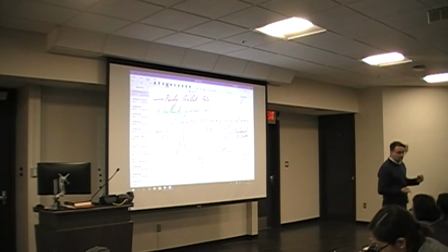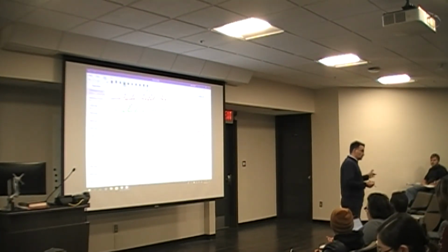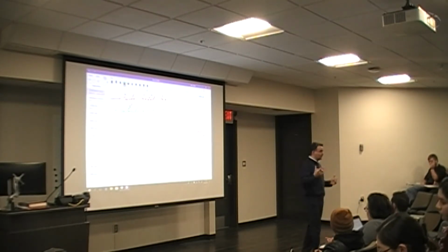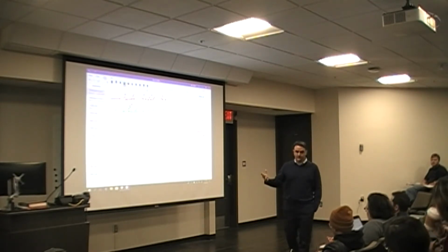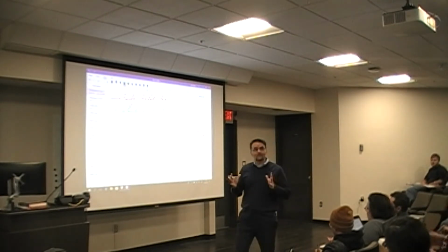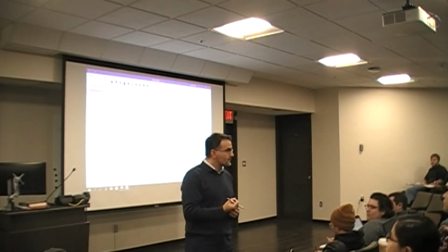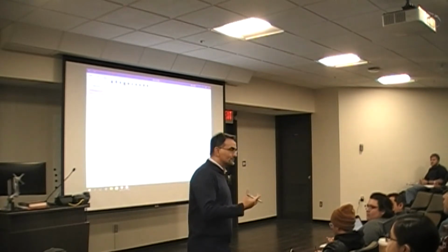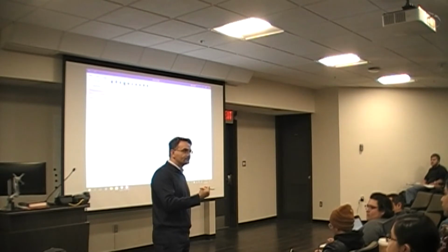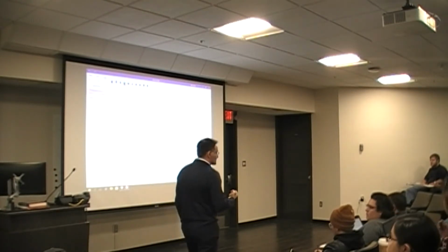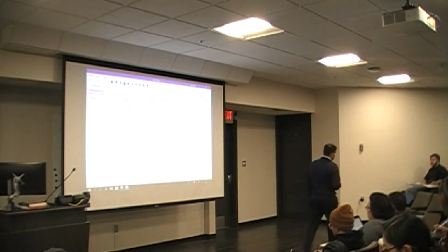What happens if they're connected to one another? To concrete, it loses its strength, it creates a weak plane. What else? What is one of the most important things that we are concerned with in concrete? We are concerned with durability. If the moisture gets in there, it compromises the bonding between the aggregate and mortar. It compromises the strength. So it creates issues with regard to the durability of your concrete.